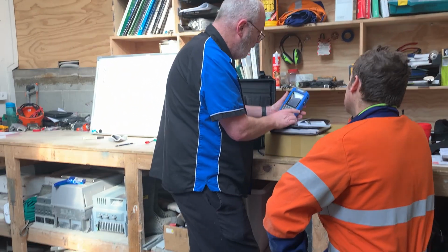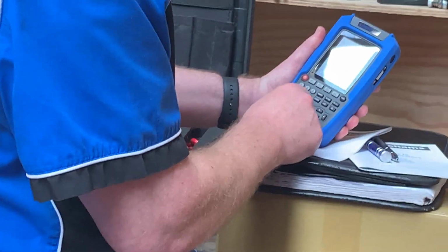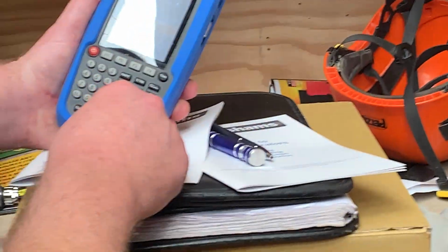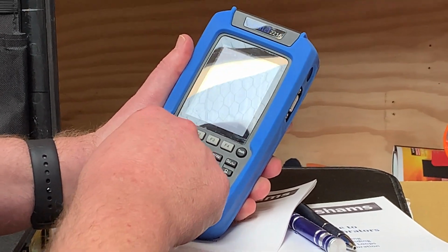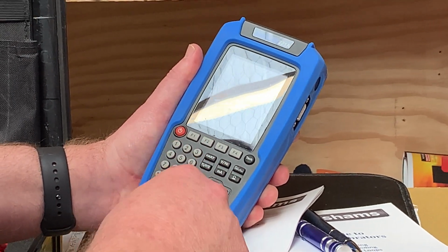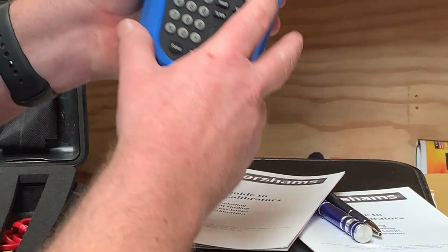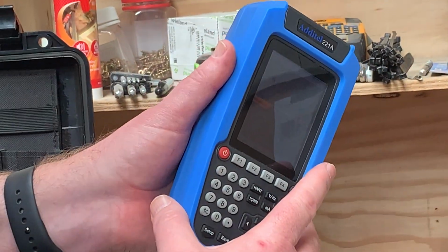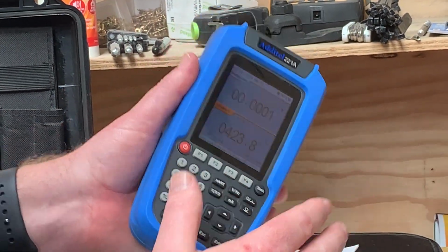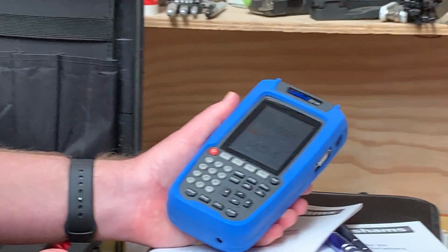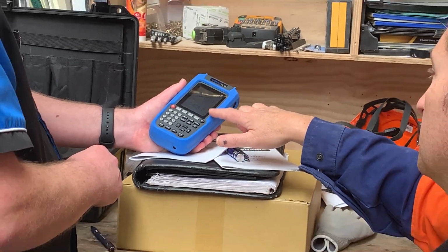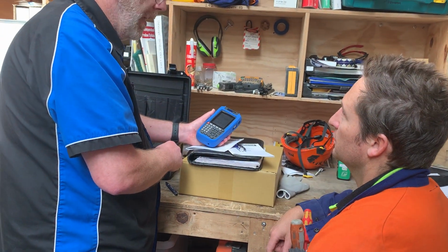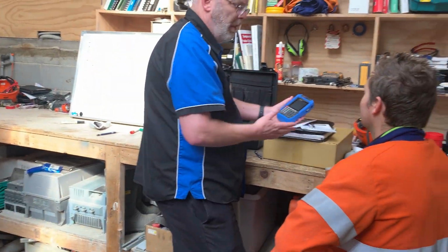So if we go to thermocouple, we're going to source a K-type thermocouple at 423.8 degrees. That is 16.474 millivolts. Always. That's what we're putting out, and whatever we're connected to needs to compensate for that. It does so automatically. You don't need to think about cold junction.